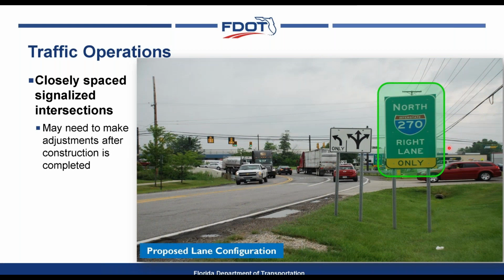So in this case, we went back and we added a sign to direct the drivers to be in the right lane if they needed to go northbound. That way we could avoid those weaves being made.